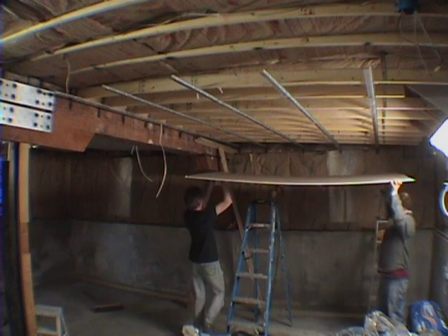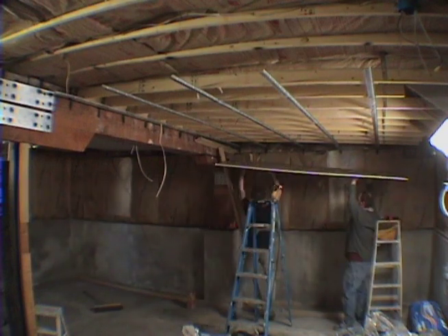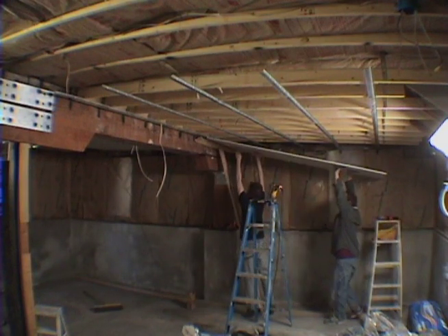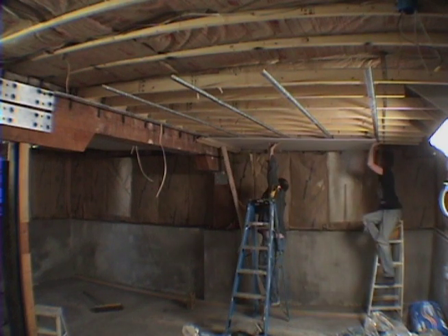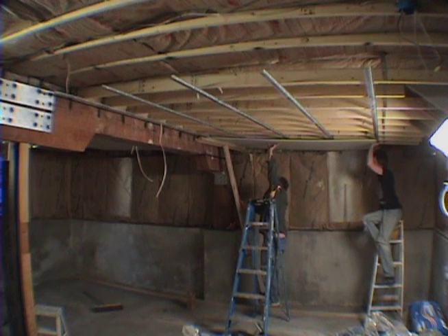Hanging drywall is much easier with 2 or more people. The ceiling height in this space is 9 feet, so we need to work on ladders. To help hold things in place, we built a support cross out of 2 pieces of 2x4, which helps hold one end of the drywall up while you wrangle your ladders into place.